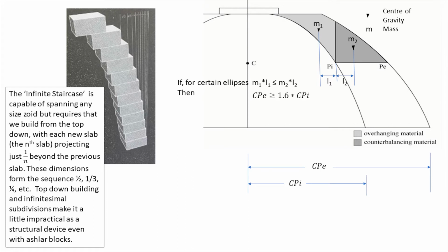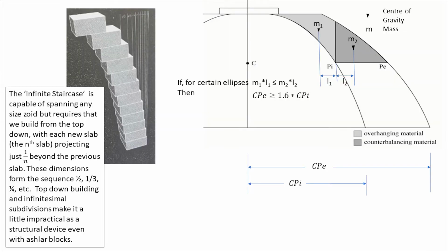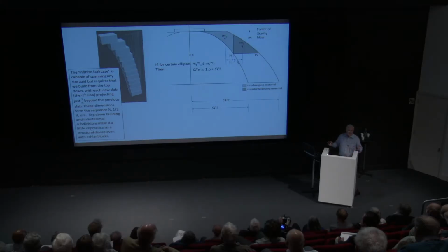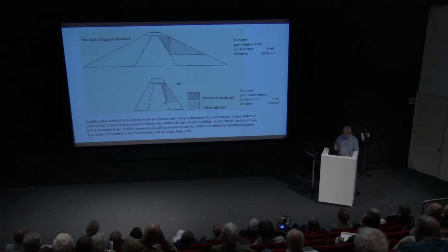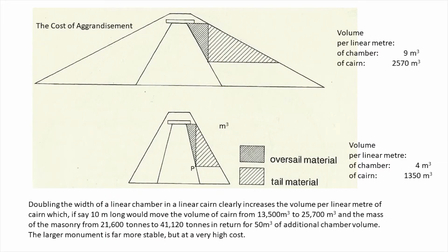I've now built something getting up towards about 100 of these with different vertical sections and in different lithologies, and the rule works. It has to. It's just basic physics. It's worked out obviously in the first instance by rule of thumb by Neolithic builders, and they could take liberties with it and make the outer wall very, very thick. But what's the limit? You can be a sloppy corbler if you build very thick walls.